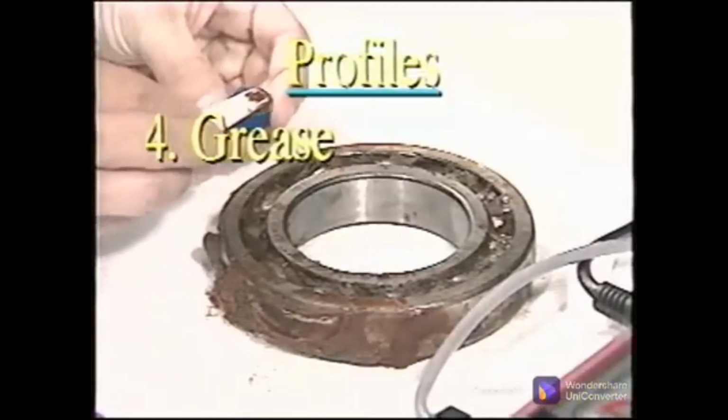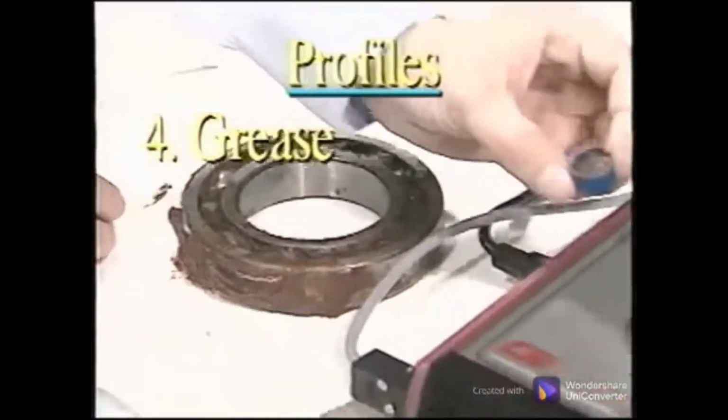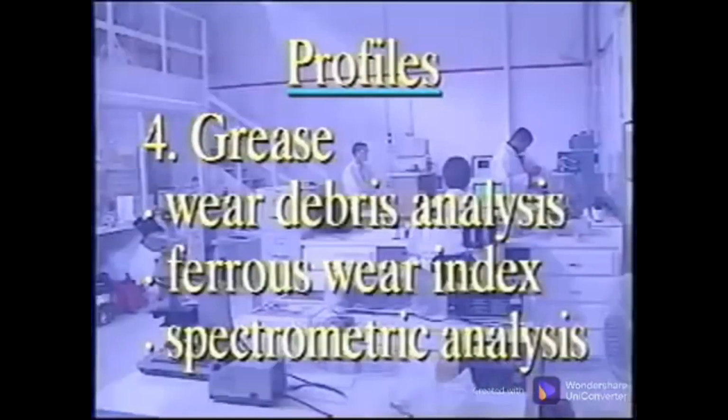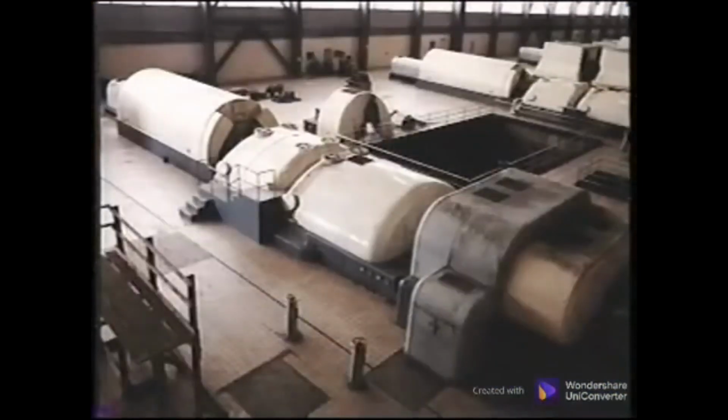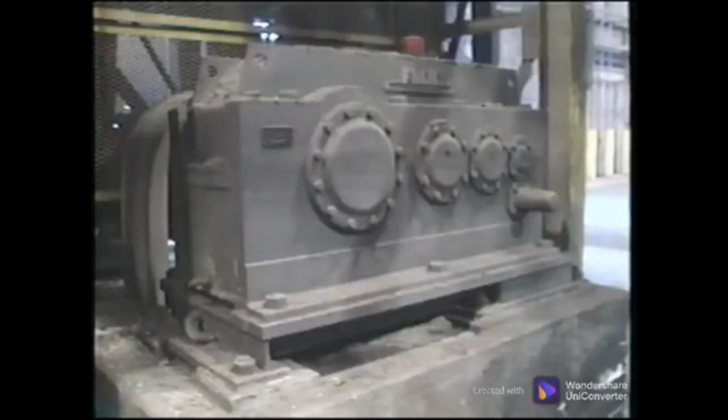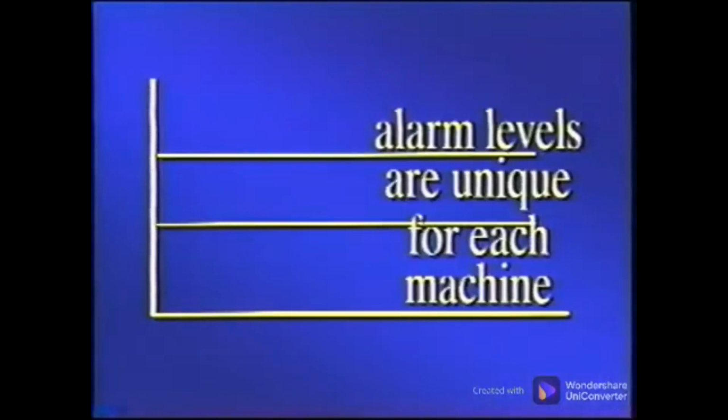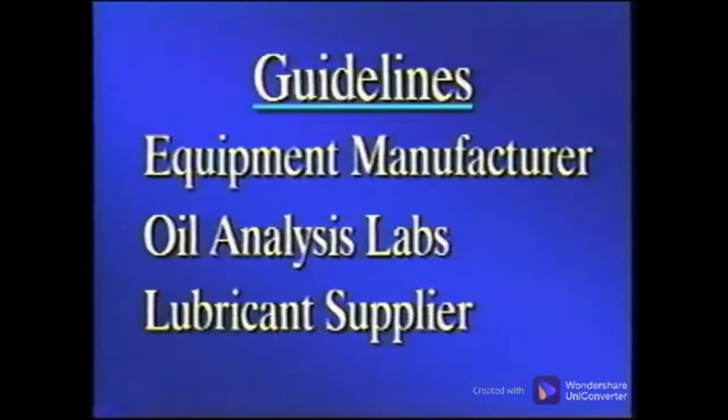The last profile is grease, which should be tested in-house with a ferrous wear monitor. Lab tests should include a wear debris analysis, ferrous wear index, and spectrometric oil analysis. All machines are not the same, and all oil tests should not be the same. And just like vibration alarm levels are unique for each machine, the oil quality levels and cleanliness levels are unique for each profile and machine type within a profile.